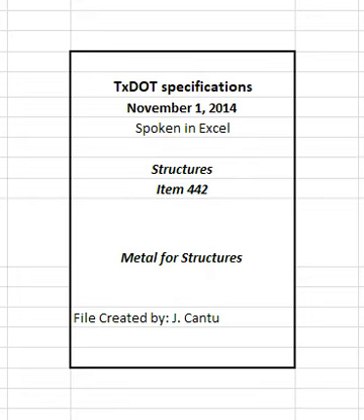Table 2. Minimum tensile properties for bar stock. Tensile strength is 60 ksi. Yield strength is 50 ksi. Elongation is 20% in 2 inches. Reduction of area is 50%. Provide certification from the manufacturer that the studs or anchors as delivered have the required material properties.